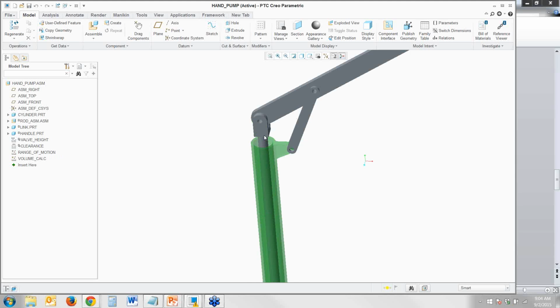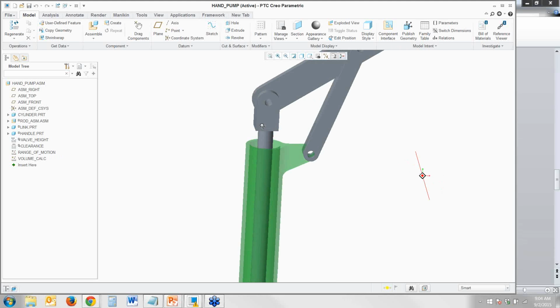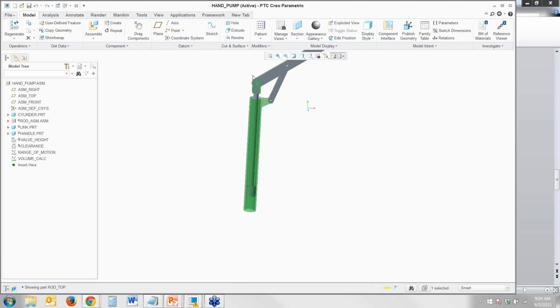Basically, we have everything defined to check, for example, the clearance between that plate right there and that green tube. We want to make sure they don't bump into each other or interfere. We have things to calculate the internal volume that that piston traverses as it moves in and out of that tube, and we want to maximize that internal volume as much as possible, right?